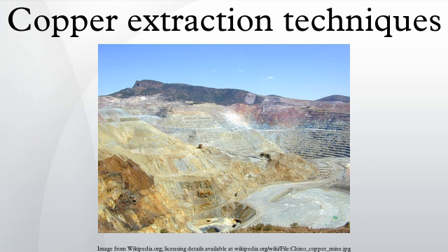Copper was initially recovered from sulfide ores by directly smelting the ore in a furnace. The smelters were initially located near the mines to minimize the cost of transport. This avoided the prohibitive costs of transporting the waste minerals and the sulfur and iron present in the copper-containing minerals. However, as the concentration of copper in the ore bodies decreased, the energy costs of smelting the whole ore also became prohibitive, and it became necessary to concentrate the ores first.